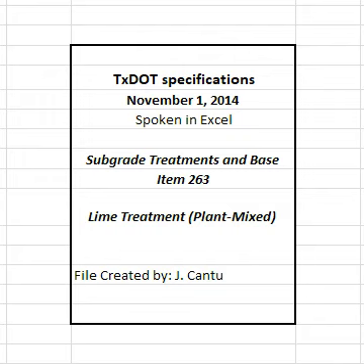Haul lime-treated base to the roadway in clean trucks and begin placement immediately. Spread and shape in a uniform layer with an approved spreader. Construct individual layers to the thickness shown on the plans, the same day as delivered, unless otherwise approved. Do not place lifts exceeding a compacted depth of 8 inches unless otherwise shown on the plans. Maintain the shape of the course by blading. Correct or replace segregated areas as directed, at no additional expense to the department.